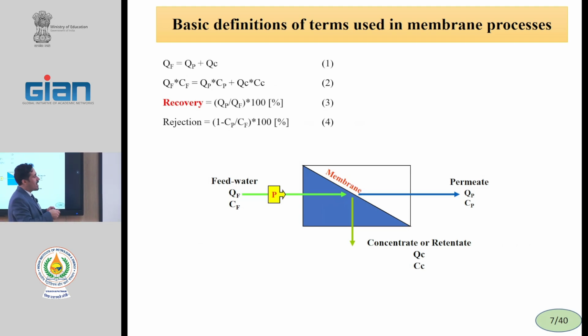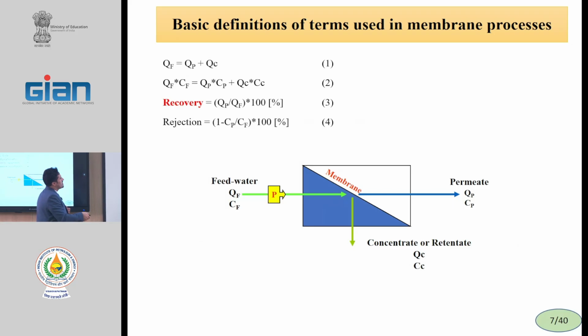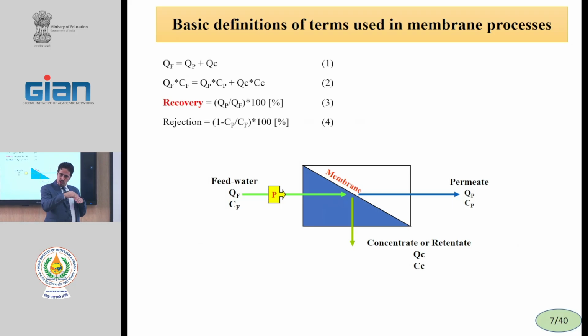And when we have a high concentration of solutes on the membrane surface, it causes high fouling. We can separate all of the solvent from the liquid, but when we do, a layer will cover the membrane surface and block all the surface, and the membrane will be destroyed. Therefore, we do not have complete recovery.